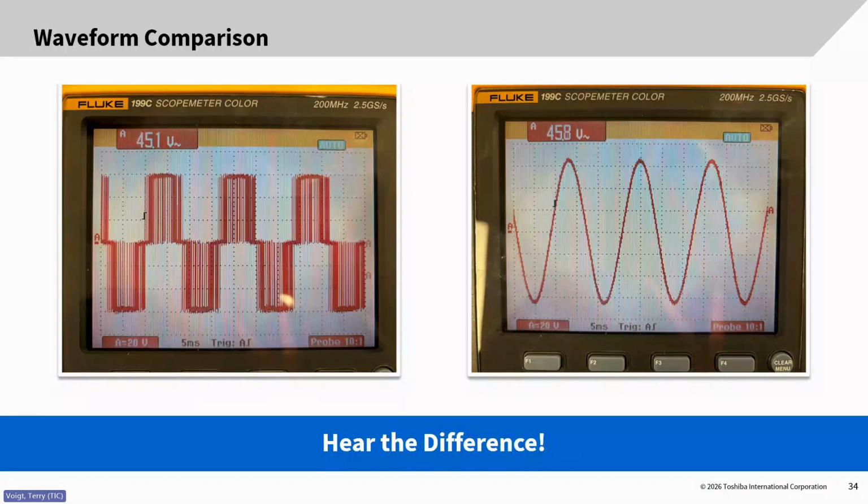I would say that looks like a very typical waveform at the motor when it's connected to a drive. And you can hear it. You can hear that ringing or singing that motors normally make. The reason we can hear that is the carrier frequency.